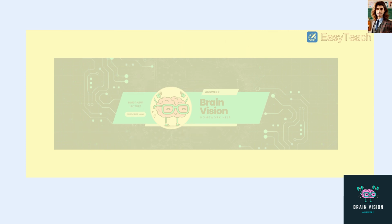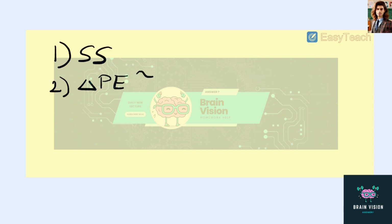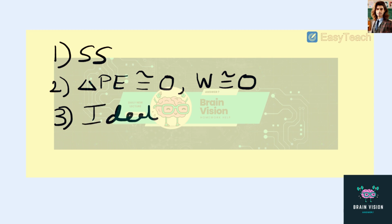So the first thing we're going to do is just write down our assumptions. We're going to assume that this is a steady state process, so nothing is going to be changing with time. We're also going to say that changes in potential energy are negligible, as is anything related to work. And we're going to assume that we're dealing with an ideal gas with constant specific heats.